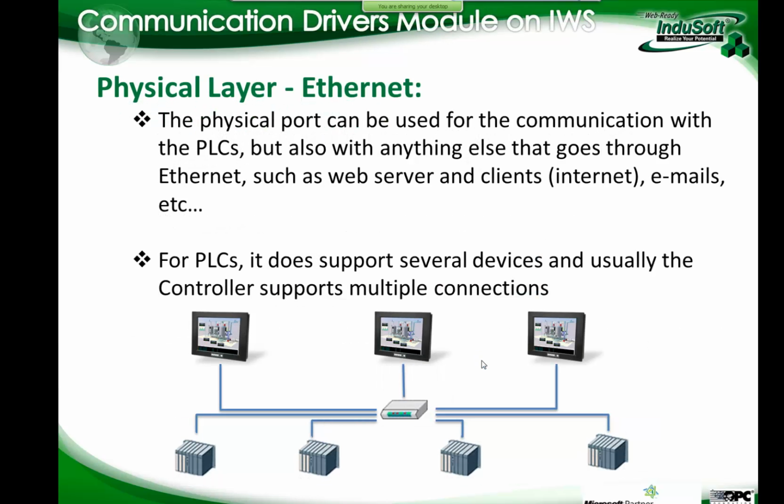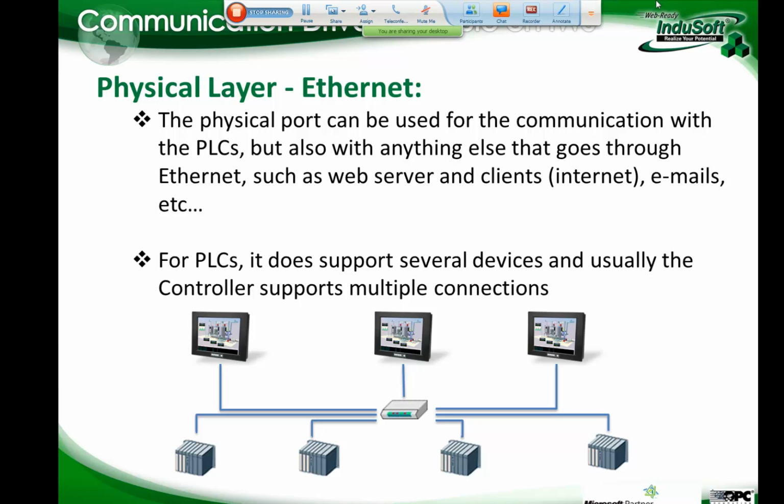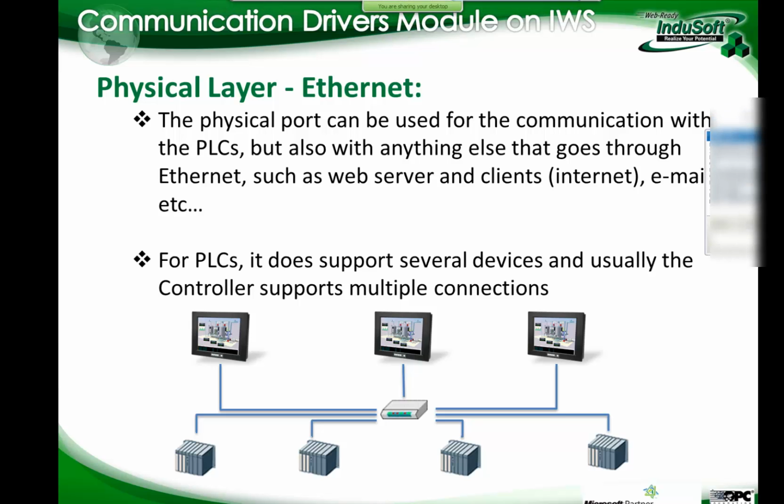And then we take a quick look at the Ethernet channel. Again, the physical port you can use for several things. I'm using my Ethernet channel here to talk to you guys. And at the same time, I'm already connected to the PLC, and I'm going to use this Ethernet channel to talk to my PLC using my communication driver as well. Okay? And a good thing when you have a PLC that supports Ethernet is that you can have multiple HMIs connecting to that same PLC, instead of having a more dedicated channel.